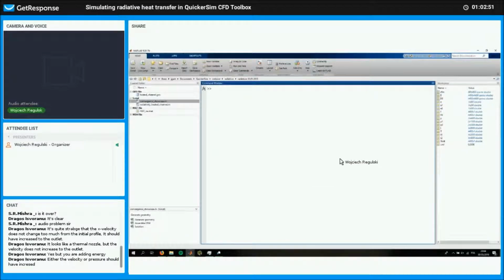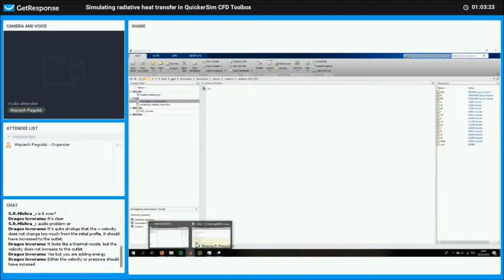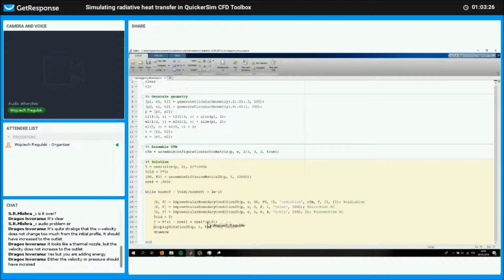If we didn't have the Robin boundary on the outside here, as you saw, it just blows up. Usually in real life applications, every body has both a heat source and a heat sink, essentially. So the stability problems are nowhere near as severe in this case. I purposely chose it to exacerbate these stability issues. So in general, what I would recommend is to always under relax your solution at least a little bit. And if it still blows up, then you can stabilize it.